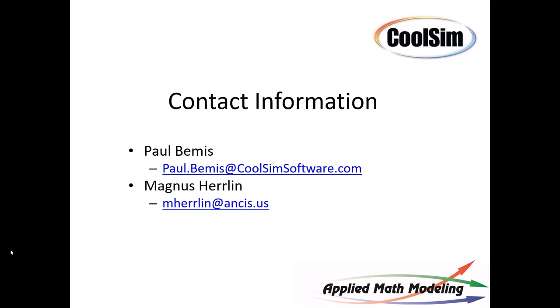MLC just compares the energy to cool the data center to the energy required to drive the IT server. So you're getting a more direct comparison of cooling energy to IT load energy. When you make a small change in MLC, to things like fans or leakage, it will show up pretty quickly. But PUE, because it has IT energy in the numerator, the number doesn't change very much, unfortunately. But it's better than nothing.